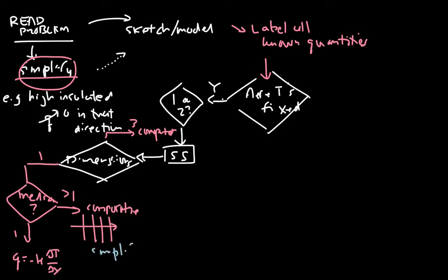Look for the layers that may be highly conductive, so you're comparing k and h values. Maybe you're going to consider any negligible resistance, and basically you'll treat this as series resistors, and you can solve it that way. So that's the one-dimensional case that would be easy for us. 3D, we need a computer.